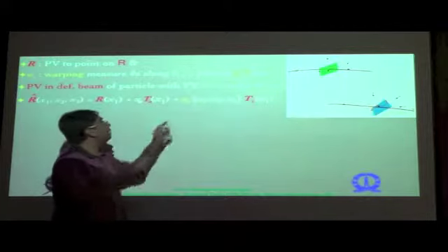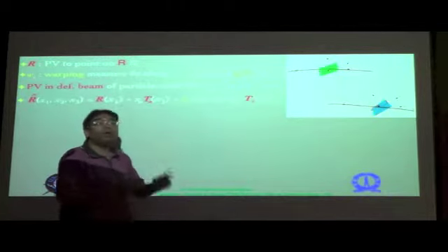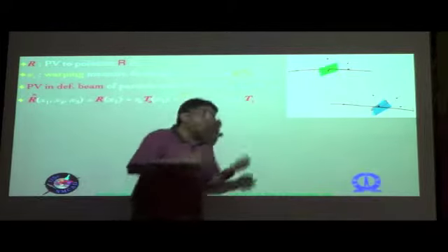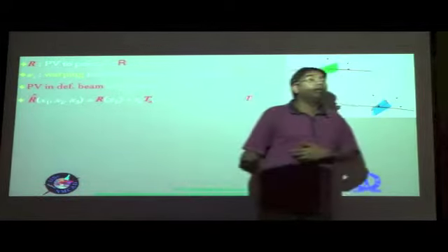The solution to that is the fact that the Wi now has a different meaning. In other words, the Wi that you had in the previous case and the Wi that you have here have a slightly different meaning because of the way the transverse shear strain is being considered. In one case it is considered with the rigid body rotation, the other case it is considered with the warping, which is what we are doing now.